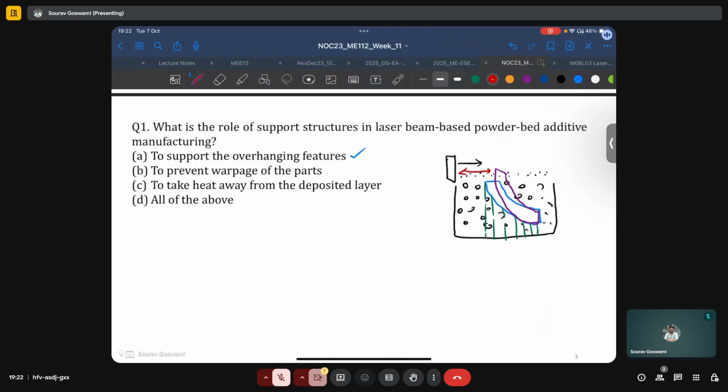It will damage the part and it will stop the printing process and send the machine into downtime. So we want to prevent any such occurrence because the tolerances here are really small. As I said, this layer thickness will only be a few tens of microns thick, and so even a small amount of distortion or warpage can lead to damaging the recoater blade.